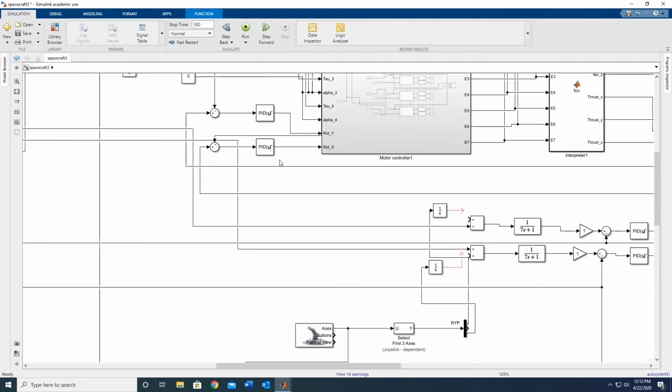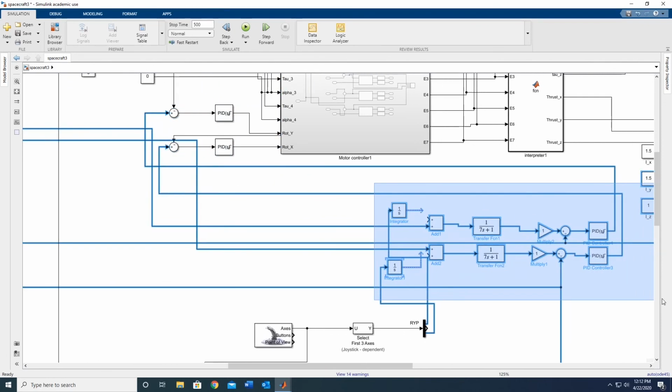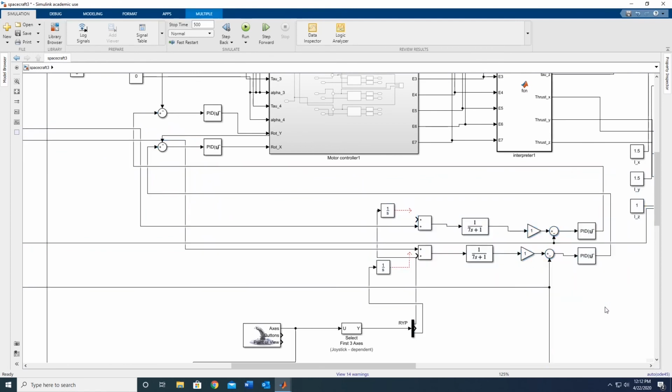This is my set of angular regulators, and then I regulate where my angular set point should be by using this other algorithm. I believe this is called servo control. I don't know that for a fact, but I believe this technique of using one set of controllers to regulate your positional, because if you have a vehicle that has thrust, if you angle it, that thrust is going to be off an axis. So you have one set of controllers that controls your thrusts in the different axes, and then you have another set of controllers that determines what that thrust should be.